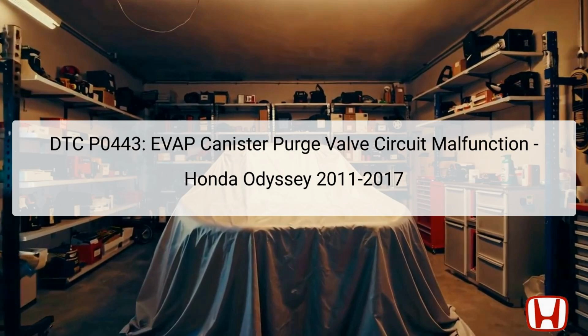intake manifold. This valve is located in the engine compartment, connected to a vacuum line from the intake manifold, and engages during specific engine conditions to allow the engine to consume the captured fuel vapors. If there are issues with the circuit or valve, it can lead to the DTC being triggered, indicating a need for further diagnostics and potential repairs.